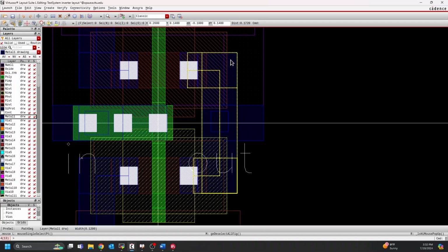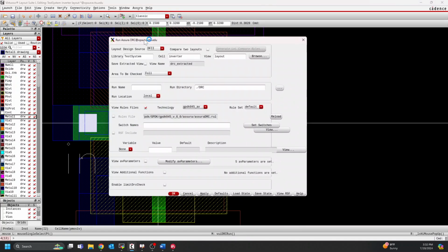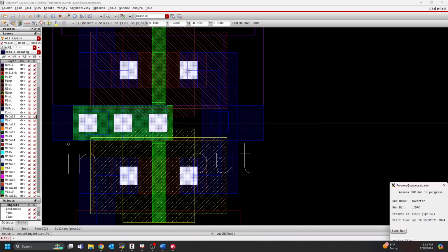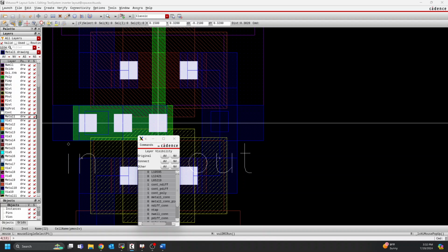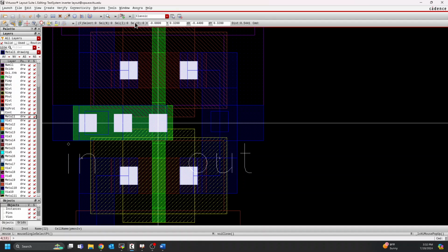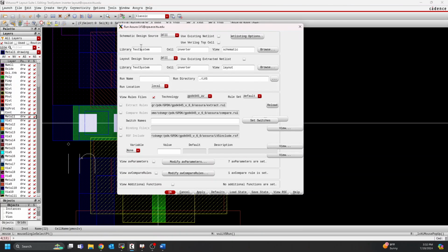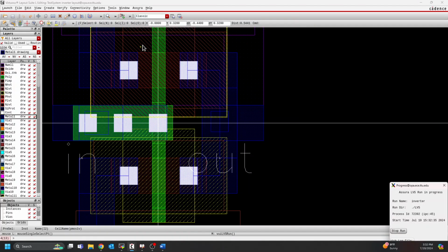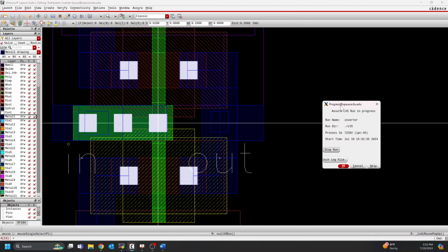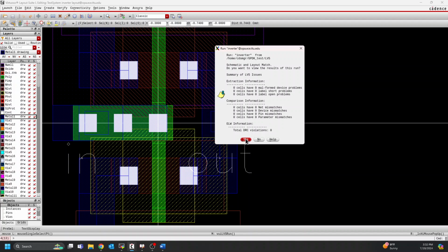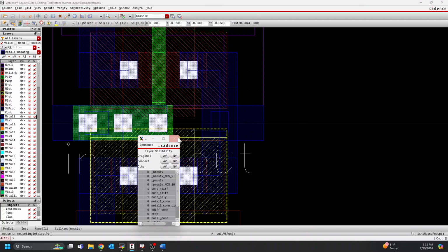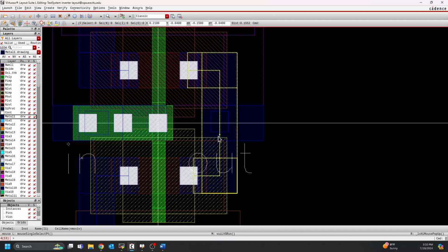Okay, so now while we're here, let's go ahead and just run DRC and LVS one more time, just to make sure we didn't violate any rules. So we can check our run. No DRC errors found, so that's great. And now we can close this guy and run LVS. Give it some time here. What we want to see is that our layout matches our schematic. So now we can just press yes here and close this guy because we already know it matches.